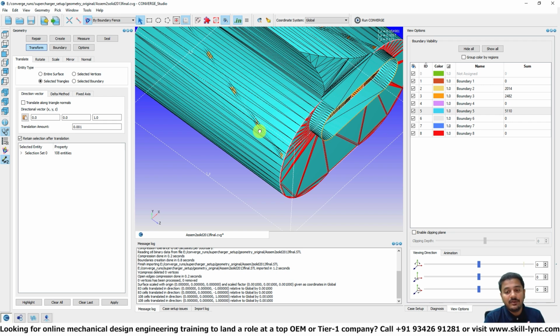The reason why we are actually doing this is, this helps you understand how you can make modifications to your geometry so that you will be able to run the CFD analysis. So one of the common things that people do is they play with these gap clearances, right? Just to see what happens. And in reality, there is no CAD model available for that. So what you have to do as a CFD analyst is apply these changes on your own so that you can tell your client or your customer what's going on with your simulation.